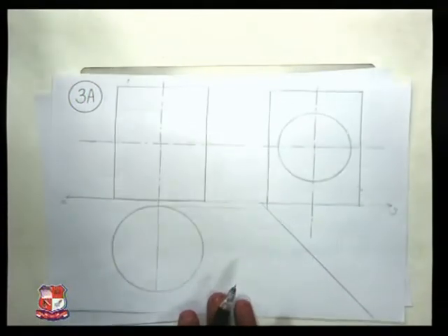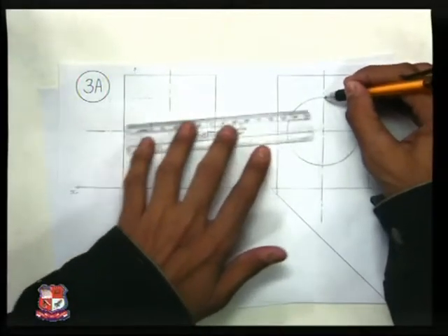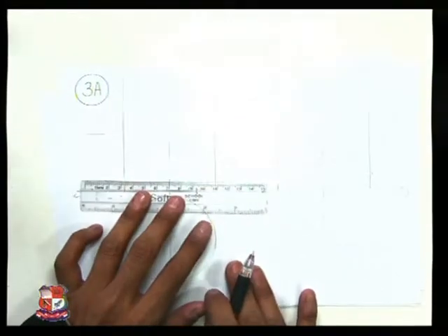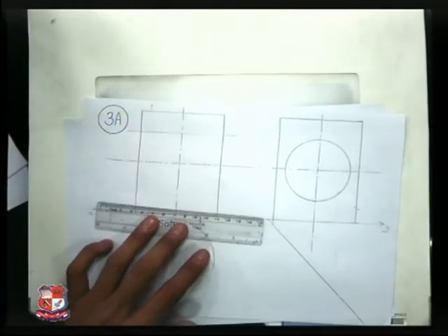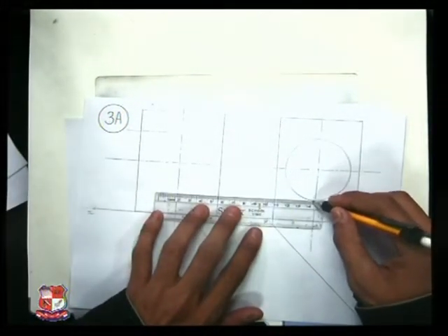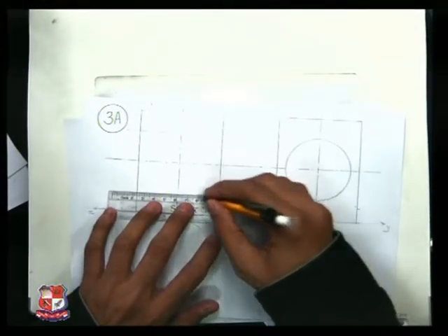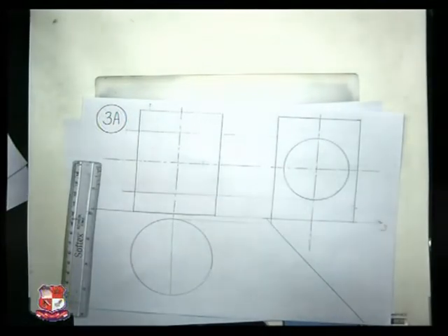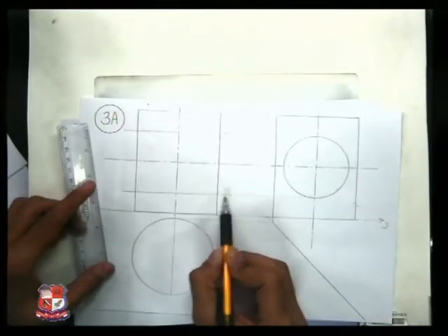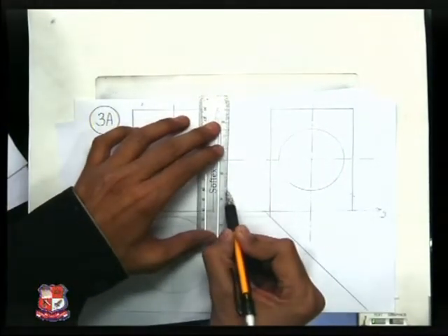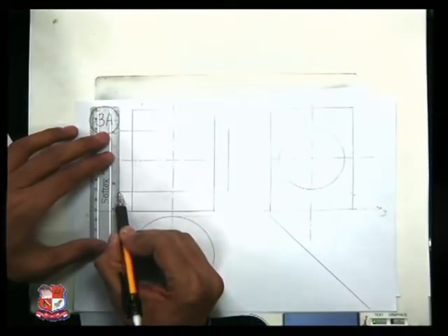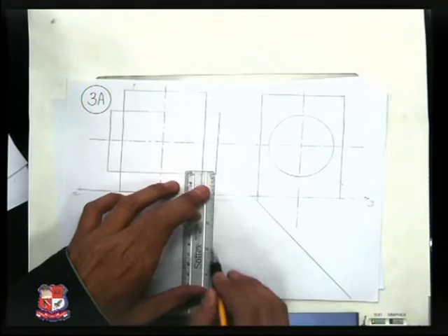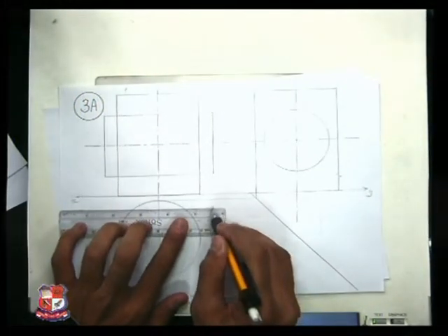After drawing the axis of this horizontal cylinder, we can draw its side view by taking projection from this end. Take projection from here and here. This is this line. Similarly from this point draw a line, take projection over here. So from here to here is another line, and the length of that cylinder is given, that is 100 millimeter. So from this axis mark a point 50 millimeter on this side and 50 millimeter on this side, and from there draw a vertical line. So this cylinder length is 100 millimeter, 50 millimeter on either side. Similarly in the top view we can draw the same cylinder, and the top view and the front view of this horizontal cylinder would be alike.